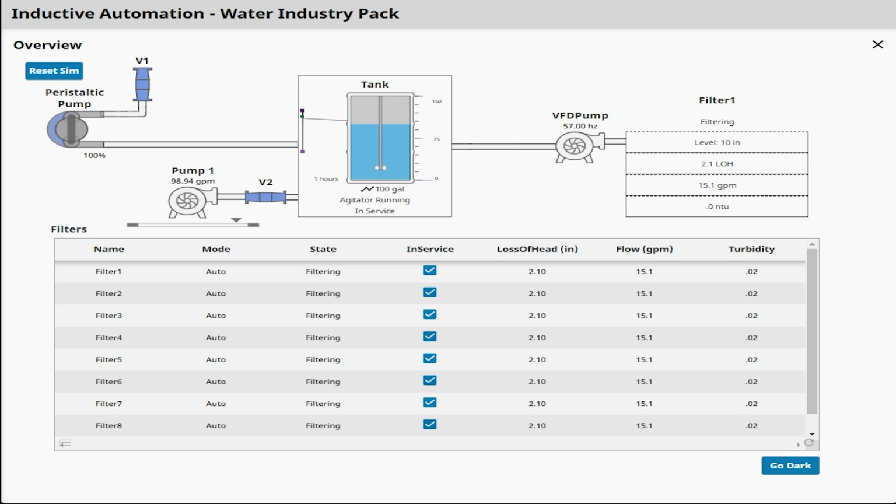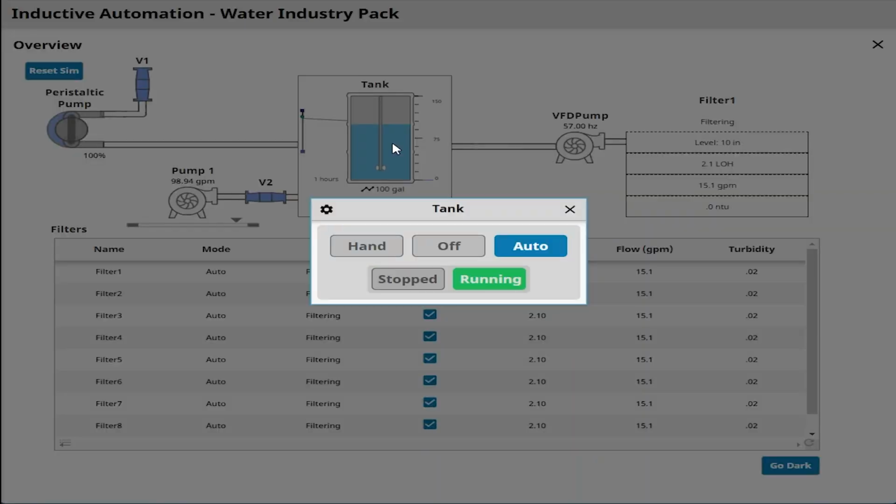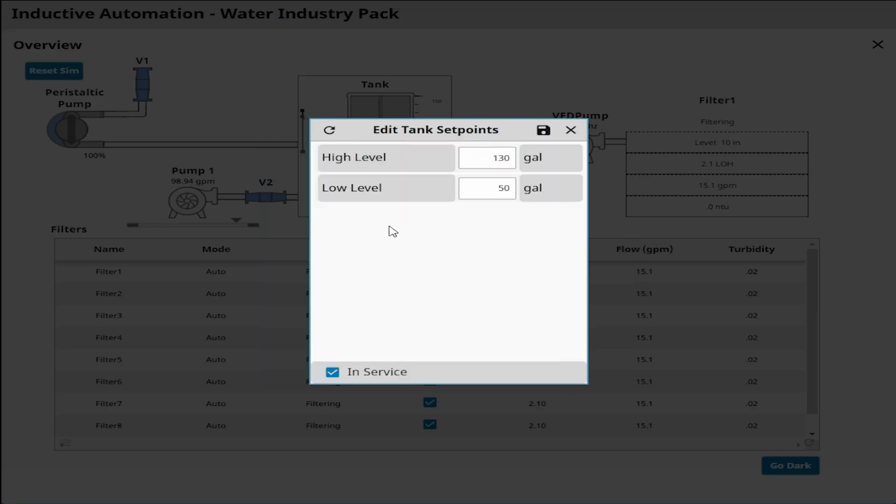Clicking most of these resources is going to open an HMI pop-up, and clicking the setup icon will open a pop-up with a list of set points for the device. These set points can drive alarms, and we use them in the HMI for changing colors based on something like an out-of-range condition. We also use them to set up the analog indicator.